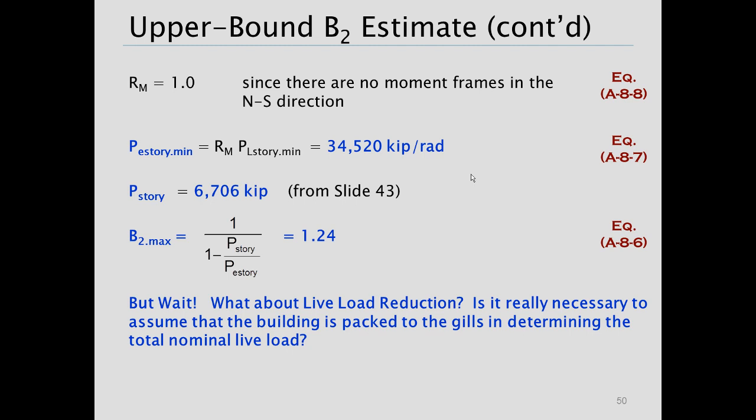Okay, good question. Yes, or another name we often throw around here is gravity columns. So we're basically assuming that leaning columns, gravity columns, and dummy columns, for purposes of our analysis idealization, do not provide any contribution to lateral load resistance.